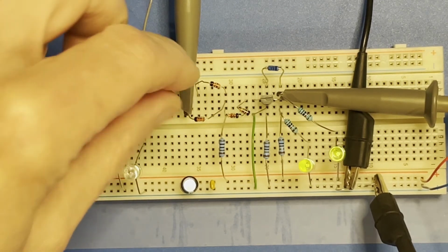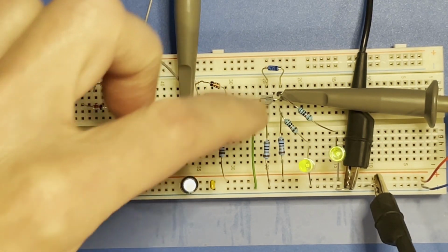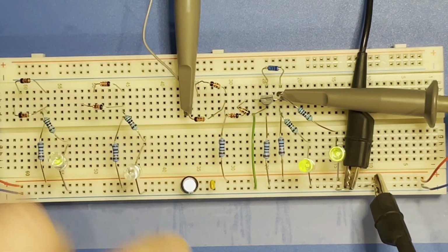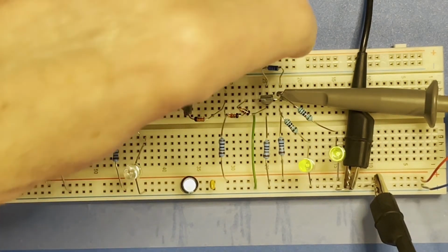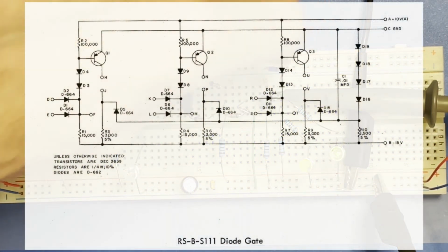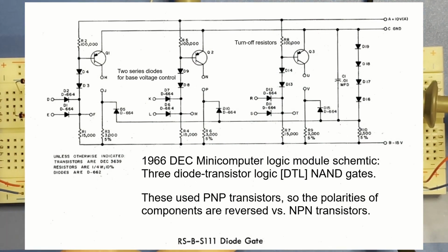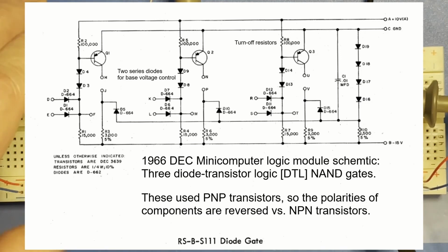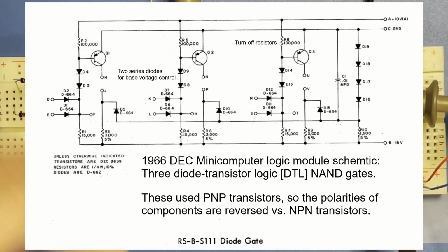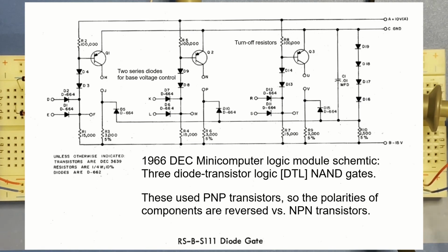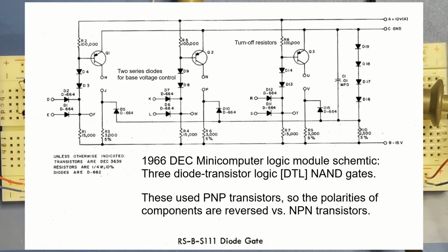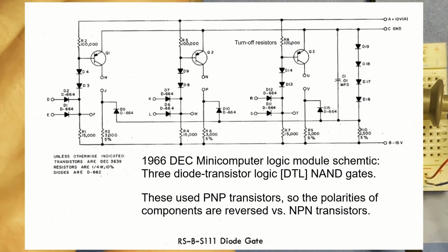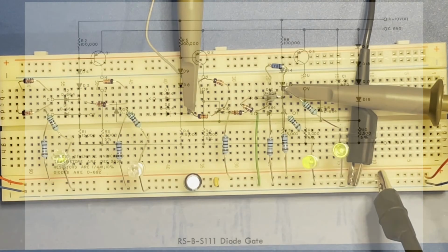And this circuit, in essence, is the type of thing, the 2 diodes and the extra resistors, not with the Schottky clamp, because that wasn't invented back then, but the 2 diodes and resistors, and in that case, multiple voltage levels and different biasing to try and limit the saturation. This is what was used in early transistor-based computers before integrated circuits came about. So yeah, it was the 1960s era, or early 1960s, late 1950s. Transistor-based computers would use this type of circuit by the thousands for all the logic functions to build a complete computer.